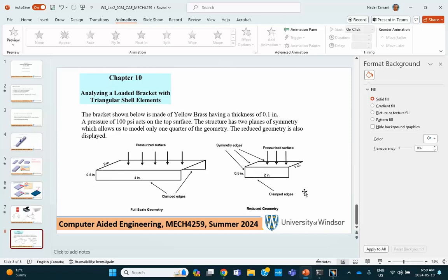Or you can make a box, either this size or that size, extract the faces that you want, such as the top and the side face, and then you have to join, because extracting the top and the side will give you two different surfaces, and they don't talk to each other when it comes to finite element calculation unless you join them. So let me do the following. On purpose, it's a bad idea, but I'm going to make a box.